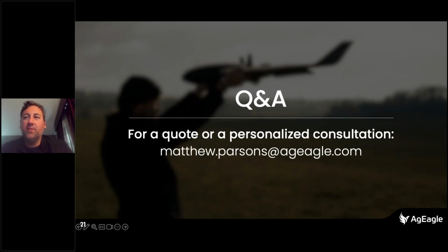Yuri asked once again about the GNSS thing, that's always quite a question. You have terrain data built into your ground control station. That's one of the things you do ahead of your mission profile. So when it is GNSS jammed, it's going to return to the point that it knew was already located in your ground control station. It basically continues to fly until GNSS does not persist. And if it continues, it's going to enact those safety protocols that are user defined. Do you have the terrain data downloaded on your ground control station?